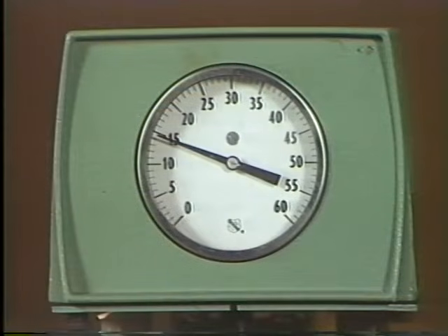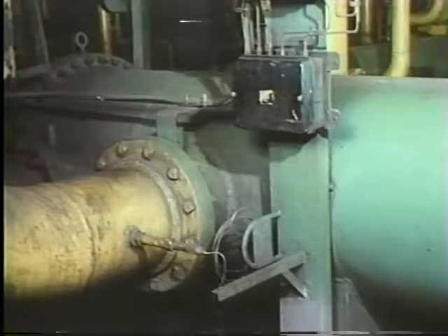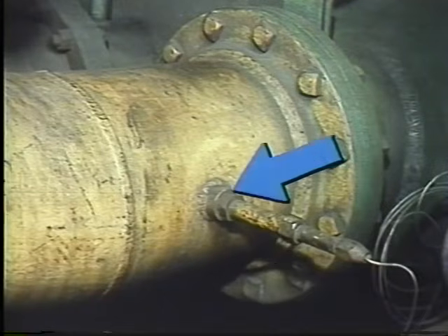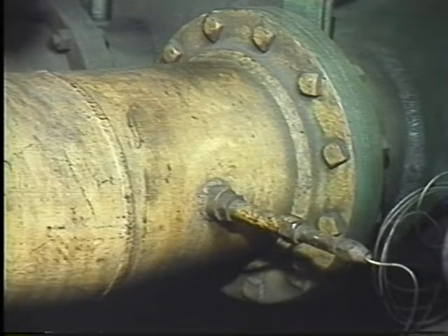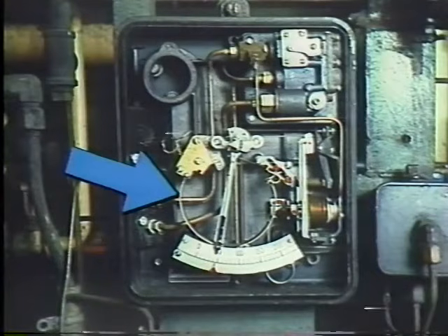Sometimes these elements are part of the transmitter. For example, a Bourdon tube is often part of a transmitter. The Bourdon tube in this transmitter senses changes directly from the process. However, primary elements can be separate from the transmitter. For example, a temperature bulb inside this pipe detects a temperature change and converts it to a change in pressure, which in turn is detected by another sensing element inside the transmitter.